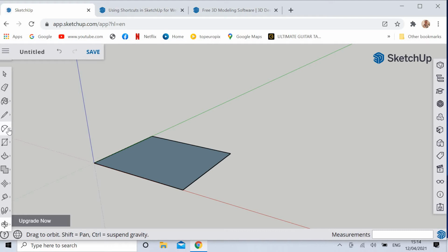For example, the arc tool. There are a number of them, but a basic arc comes up when you hit A for arc. SketchUp is brilliant. It always tells you when you're on your midpoint. So we're just going to go from a midpoint over tangent to the edge. We could go to the midpoint. Yeah, let's go to the midpoint. And we click that again. Now, we call up our eraser and watch as we clip that off. We've now made a shape. Let's say we didn't want it curved. Let's say we wanted a straight line.